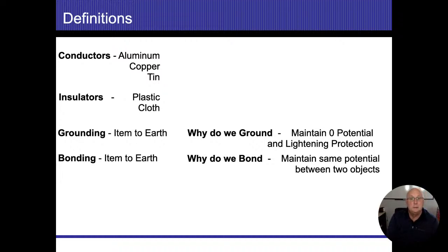The reason is there was something called aluminum creep. When it got warm, the aluminum wire would expand, and then when it cooled off, it would shrink. So the more it got used, the bigger it got, and the smaller it got. That actually loosened up a lot of the screws that held the wires together. Because of that, there were fires that happened in homes, and the fire investigations during their cause and origin determined that it was because of the aluminum wiring that was in the house.